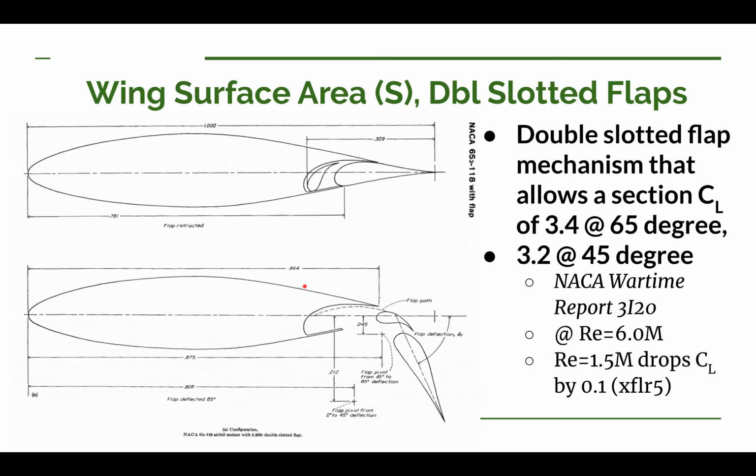This should keep the boundary layer of the airfoil attached to a very significant angle of the flap deployment. Now let's talk a little bit about what the study found. You can get up to 3.4 lift coefficient when it's deployed to 65 degrees.